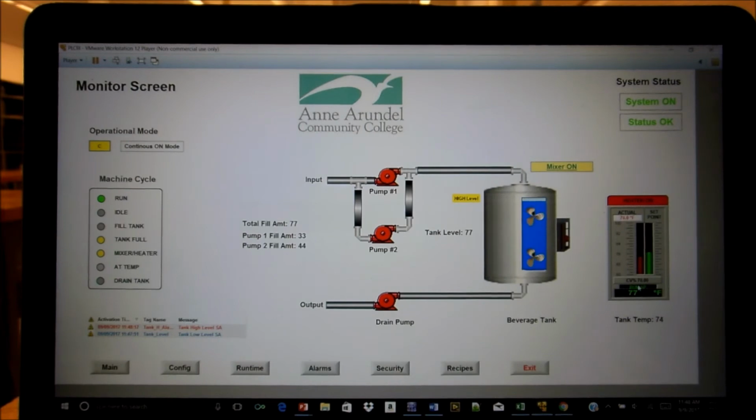So when it gets to 77 temperature, and we're at 75 right now, the heater will turn off and this will run for an additional 11 seconds. And that's what it did. Now, that'll keep running and that'll be fine.